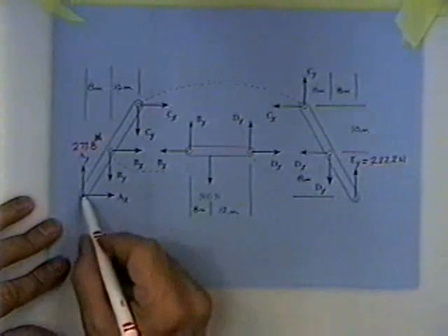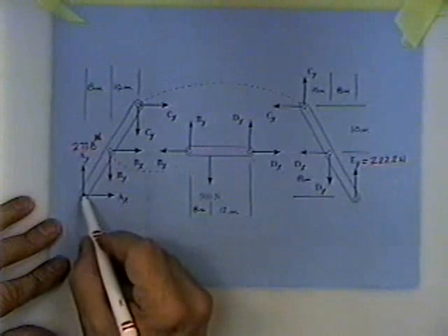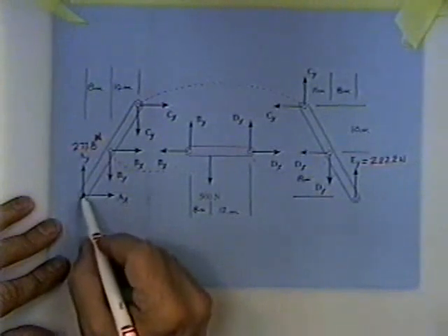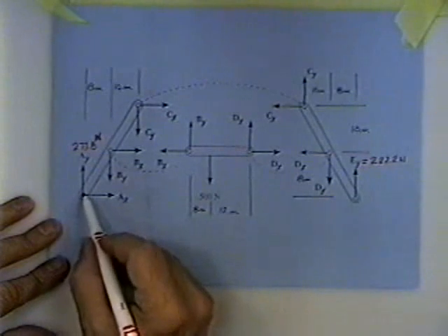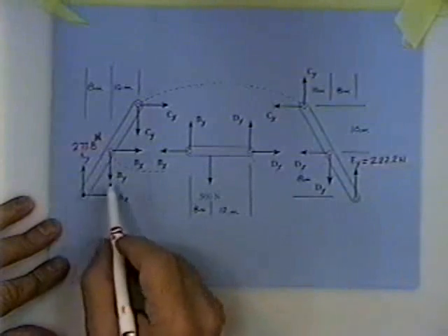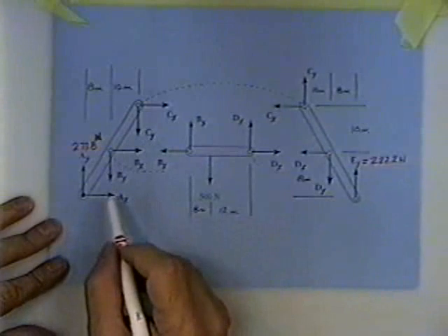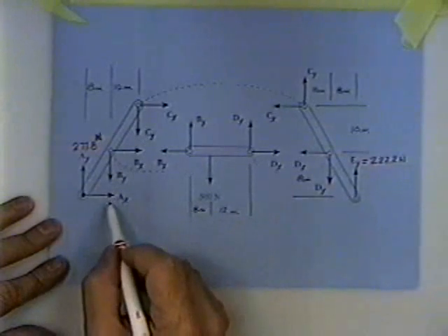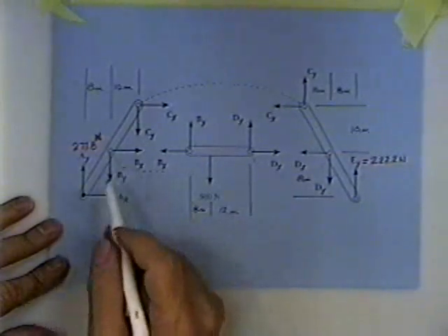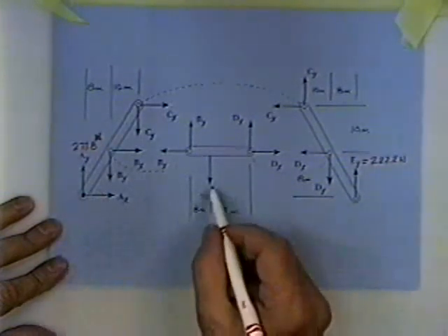This slanted member would be a horrible choice. If you sum moments about A, you have 4 unknowns still having moment arms. No answers are going to come from that. No good's going to come from that thought. If you sum forces vertical, you have 2 unknowns. Not a good choice. Sum forces horizontal, 3 unknown horizontal forces. Not a good choice. Slanted members should be left till last. Pick a horizontal or a vertical member.